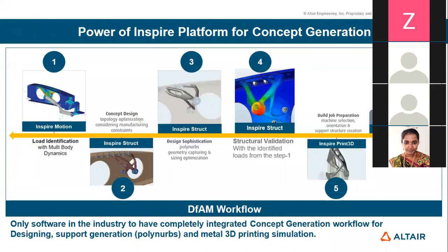So here I have put a workflow. Workflow means if you don't know about the loadings, then you have to do some kind of motion analysis, just to identify how much load your component is getting. If you know it directly, then apply it directly. So with the help of Inspire, we have done the topology optimization. Topology optimization means getting the initial design. If you are not sure about the software-given design, then that optimized part you can also analyze with any software, any tool you like.